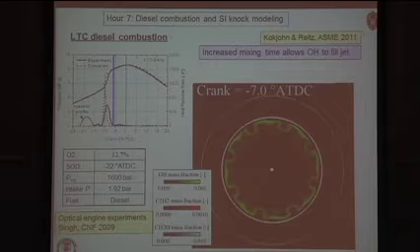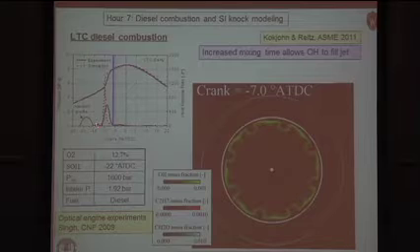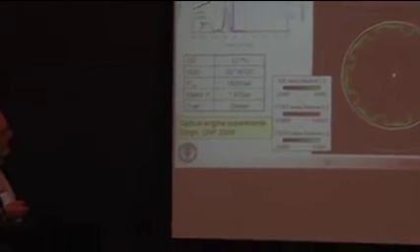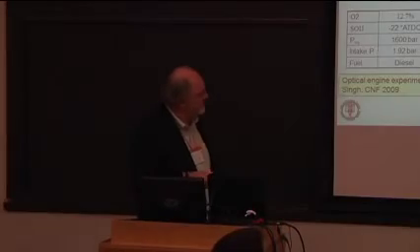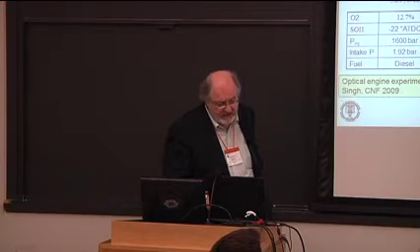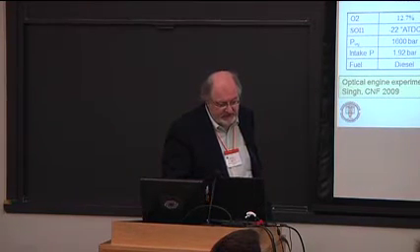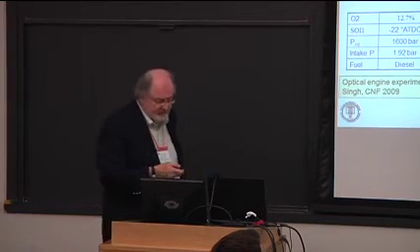And then finally we're done. So basically, because we have a lot of time for mixing, we saw the formaldehyde first, and then we saw OH, which pretty much filled the entire jet cross-section. So that's a big difference between high-temperature diesel combustion and low-temperature diesel combustion.